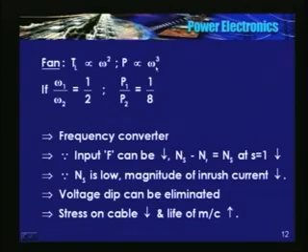Now if you want to reduce the discharge through the pump or reduce the air delivered by the fans, and I am not talking about the 60 watt fans, I am talking about high kilowatt fans that are used in the industry, what will you do? Either you use dampers, in other words dampers provide a resistance to the flow of air, or use a throttling valve for the pump to reduce the discharge.